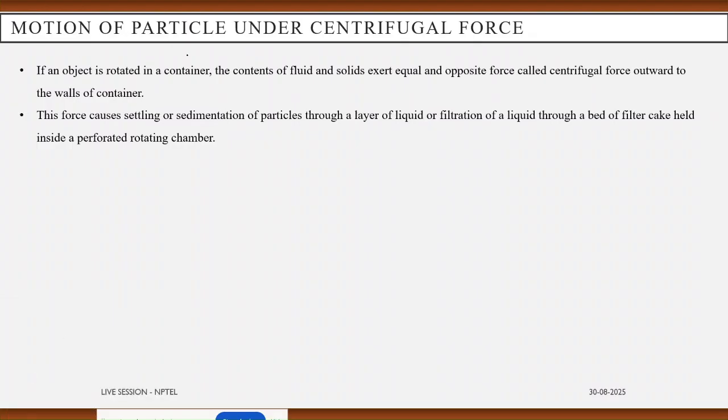Now, when we are talking about particle motion under centrifugal force, if an object is rotated in a container containing fluid and solid, it exerts an equal and opposite force called centrifugal force, which is outward toward the wall of the container. This force causes settling or sedimentation of the particles through a layer of liquid, or filtration of a liquid through a bed of filter cake held inside a perforated rotating chamber.